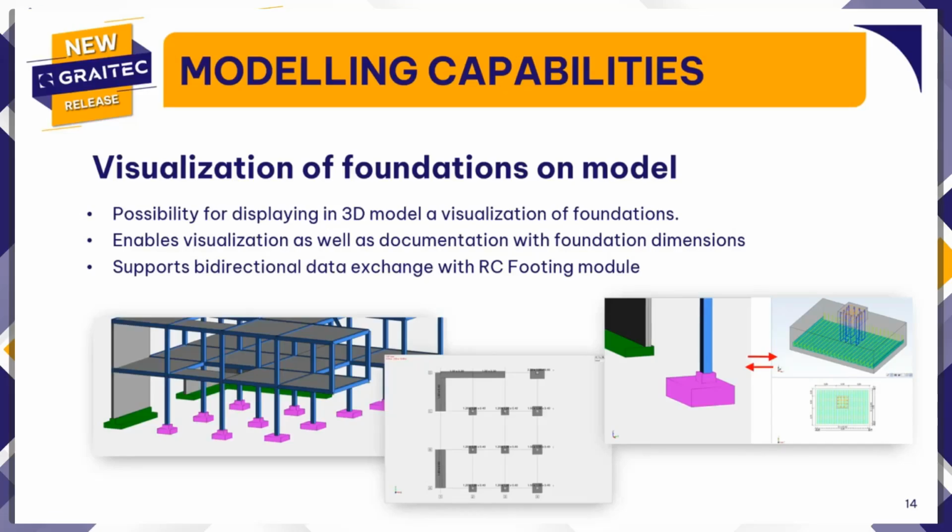Okay, the next novelty is the possibility to display foundation visualizations on the 3D model. To this effect, for the selected supports, you can set that they are foundations. This way, you can see the real dimensions of these foundations when displaying the render views. Basically, the dimensions are based on the values available in the support properties. In general, it allows for better presenting models and preparing nice documentation with foundation dimensions.